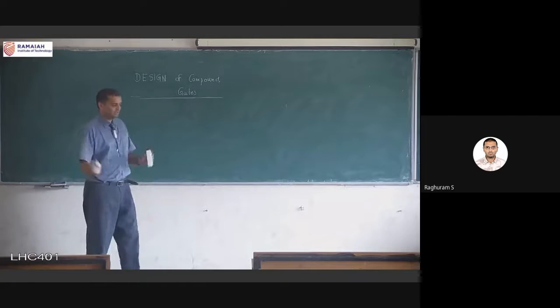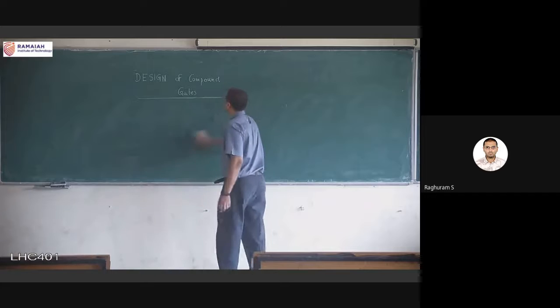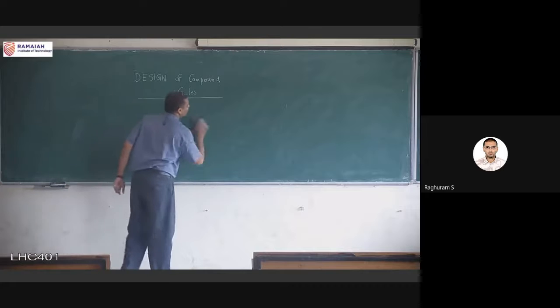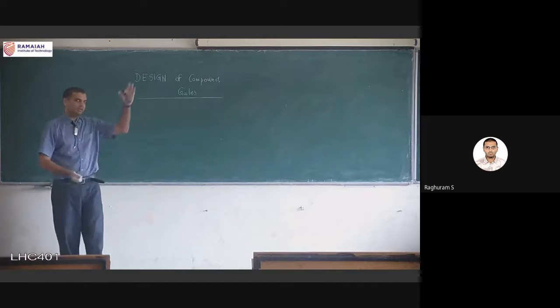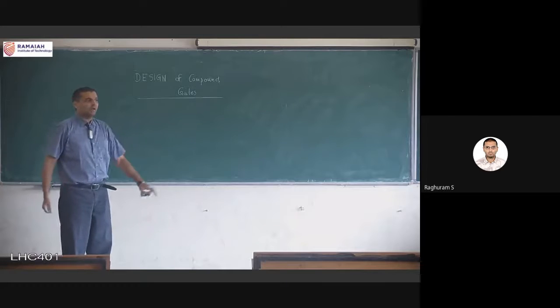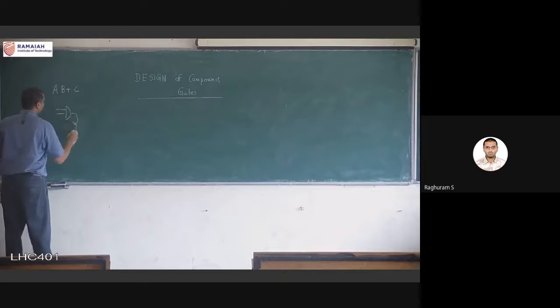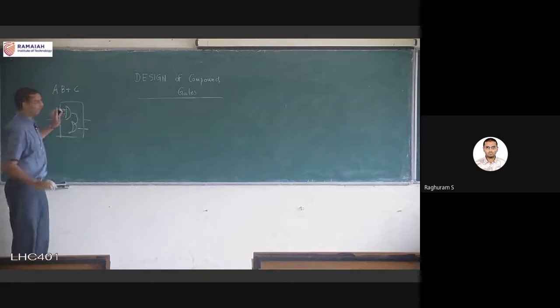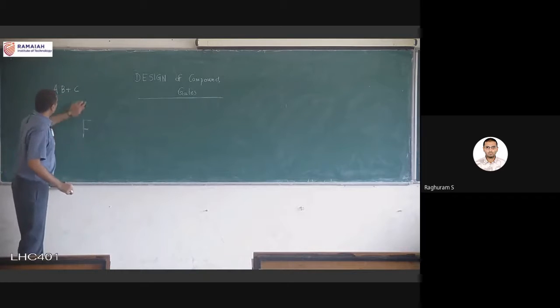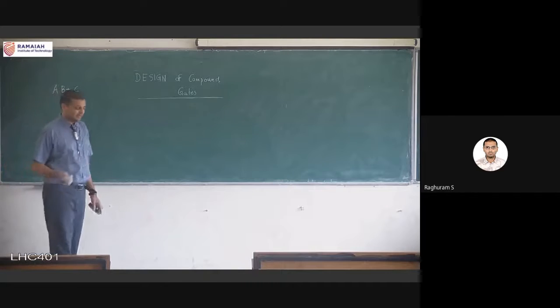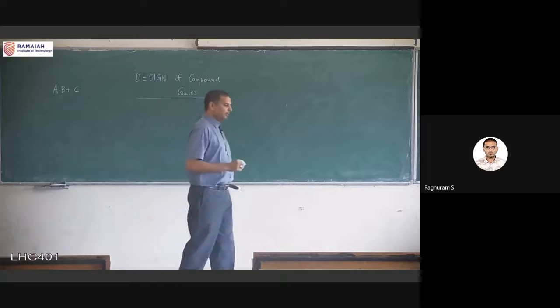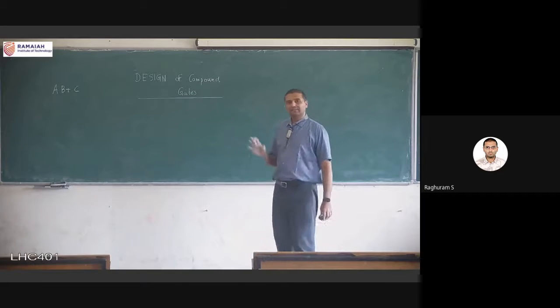Compound, nothing too complicated, just means that for any arbitrary logic function, how do we translate it into a circuit? Again, the gate is the logical expression. If I have some AB plus C, I don't want a gate that looks like this. This is not my objective, even though it says compound gates. What I am looking for is the circuit. In static CMOS family, how do I follow all those rules and design my circuit level diagram?